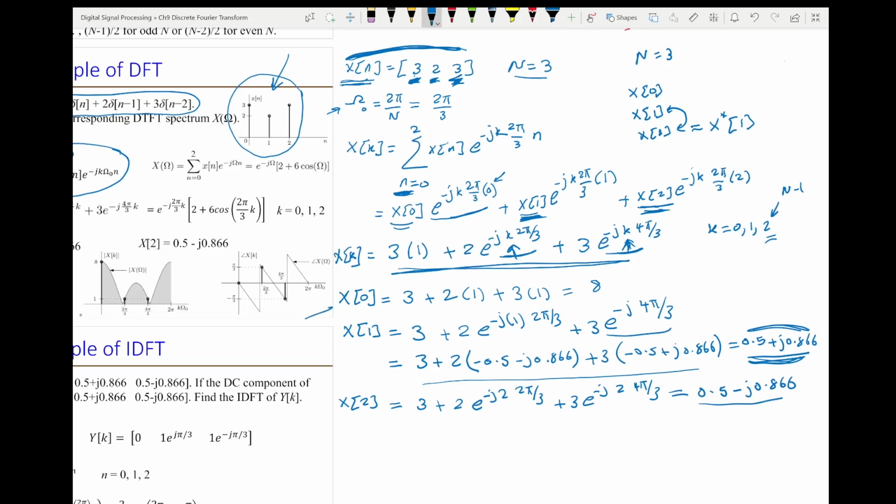So that is the strength of the DC, and this is the strength of your harmonic, which is 2 pi over 3. Now, if I want to know what this 2 pi over 3, which is radians per 3 samples, means in hertz for an actual physical signal in the continuous, analog domain, then omega 0 equals the digital omega times the sampling rate. 2 pi over 3, let's say the sampling rate was 12.